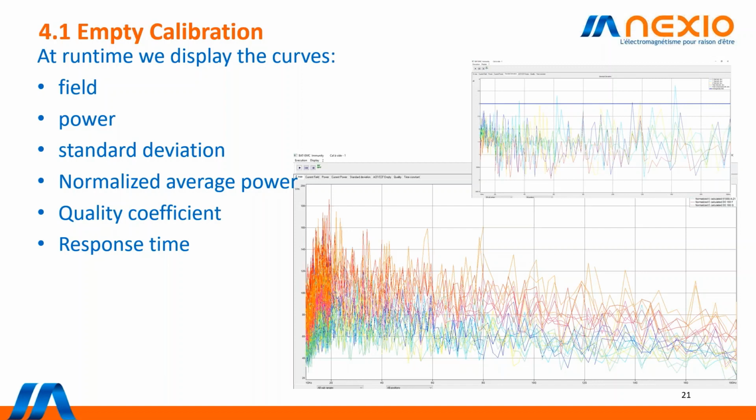The only difference is we'll need to wait the dwell time, the same as the time for a complete rotation. So at the beginning of the test, we'll activate the rotation of the stirrer with the speed, and after we'll go frequency by frequency, and at each frequency, when we reach the target, we will wait for one complete rotation. So we'll wait 15 or 10 seconds at each frequency.